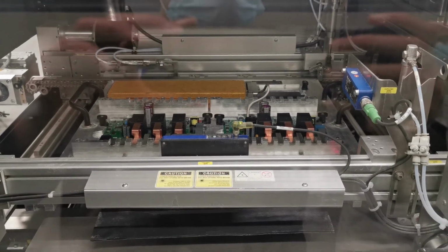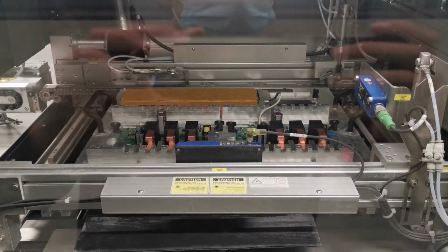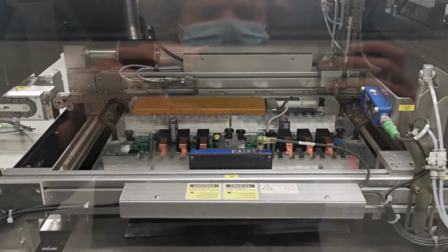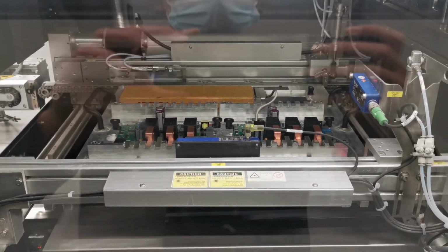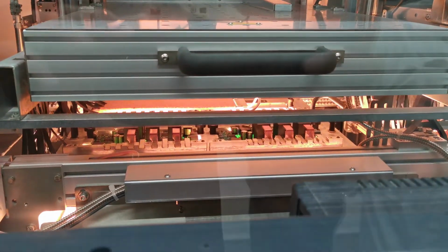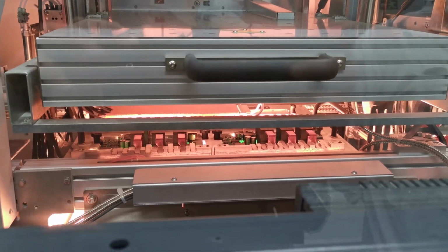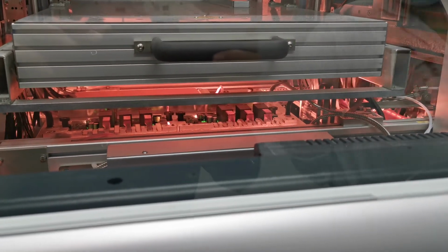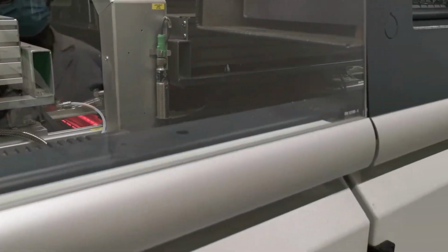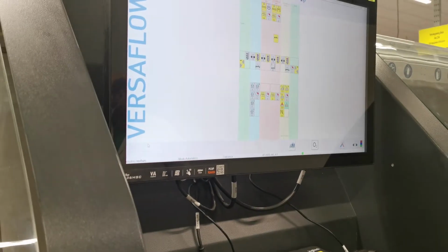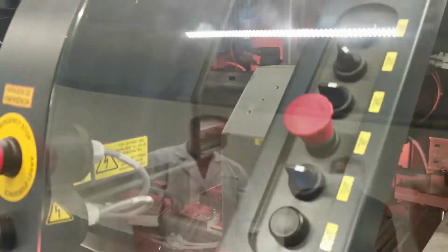In this video, we are displaying one example of profiling a selective solder process in a selective solder machine. Your machine may be different than this example and present different challenges with handling the profiler. It is important to carefully verify that there are no mechanical or other interferences to prevent you from profiling your selective solder process. On this video, you will see the profiler being carried on the same board pallet as the profiling board.